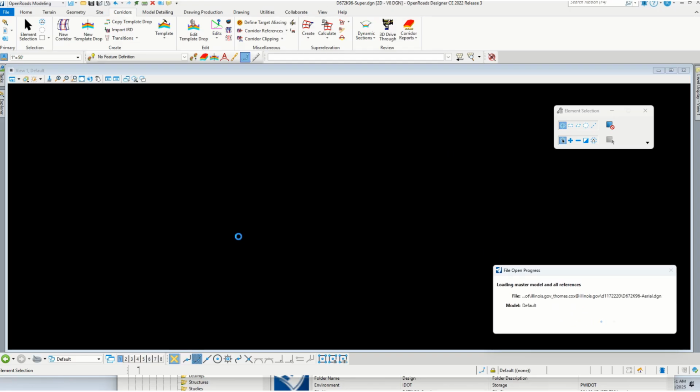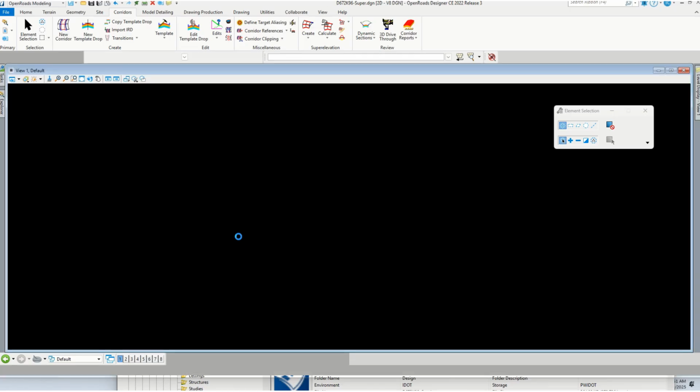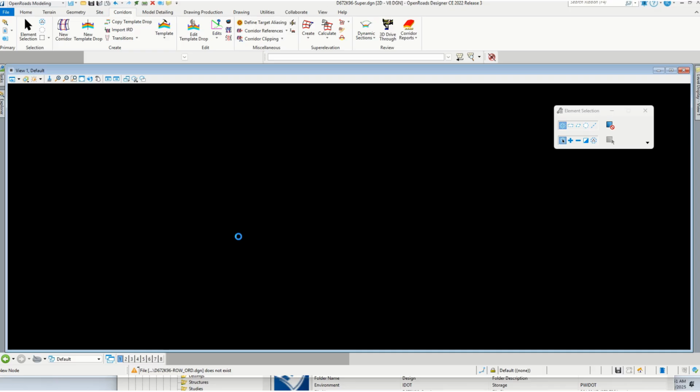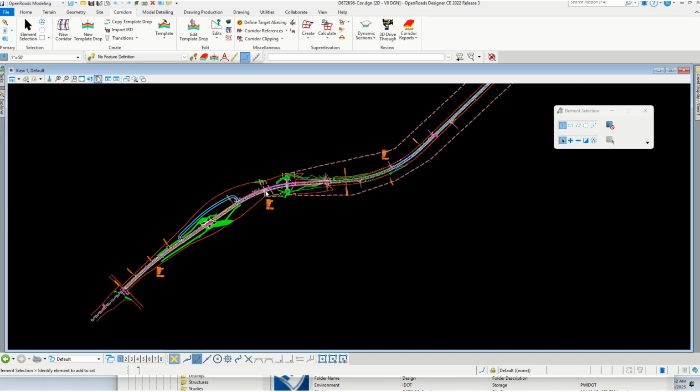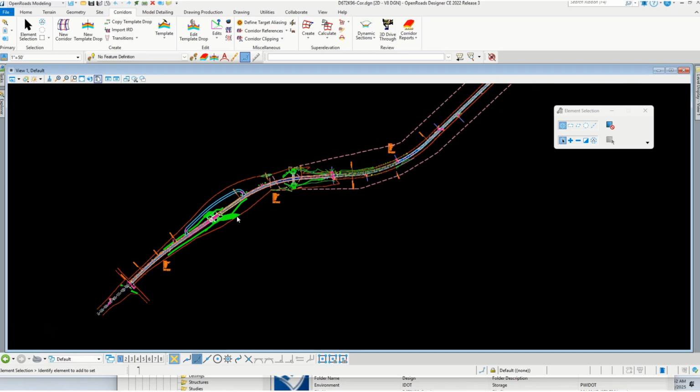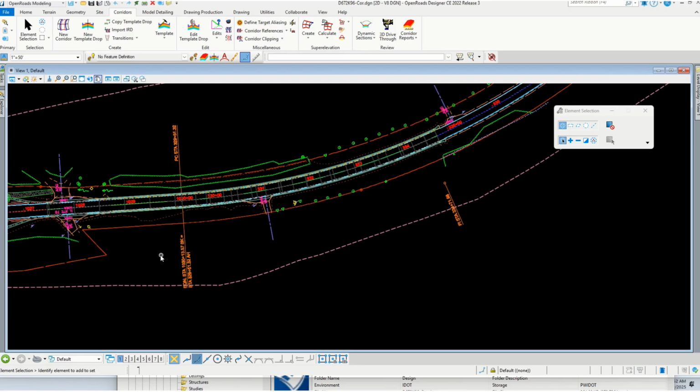The way that it's overriding that information is something called a point control, that we can talk a little bit about later. Because really, with that calculated super elevation, that's what we're doing. We're controlling the point. Remember, we created those points at 12 foot at a 1.5% cross slope, and we are going to control that point. We're going to override that point.